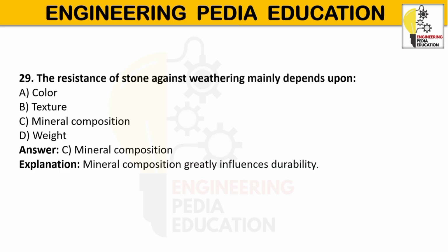hardness and other properties. Common minerals in stone are quartz, SiO2, for hardness and durability; feldspar, for strength and stability; mica, which gives flaky structure, and excess mica is undesirable; calcite, CaCO3, main constituent of limestone and marble; iron oxide, which imparts red, brown or yellow color. Importance: affects strength and hardness, influences weathering resistance, determines suitability for construction.